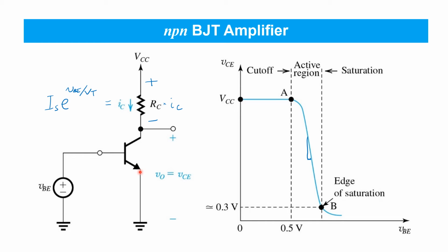And the transistor would quickly overheat. So in practice, for practical values of current, it's really only worth considering this input-output characteristic up to values of VBE a little bit greater than 0.7.